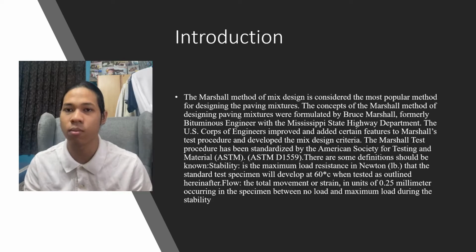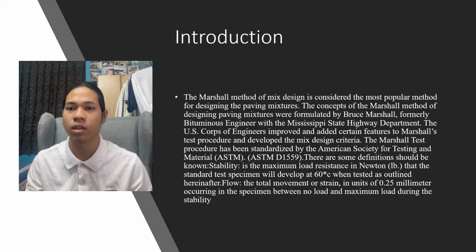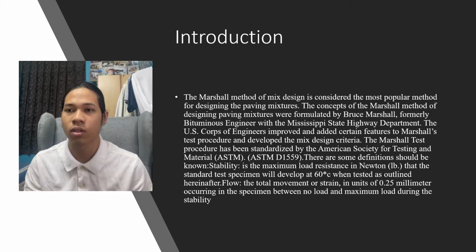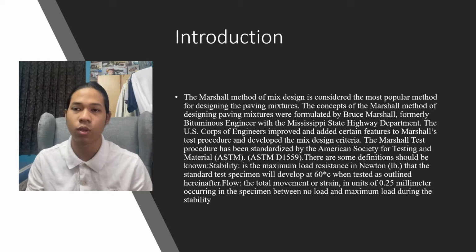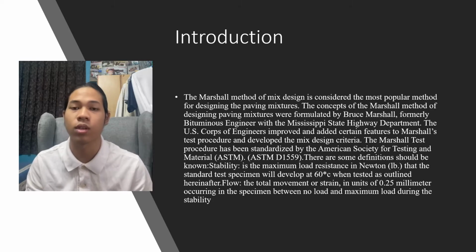Stability is the maximum load resistance in Newtons that the standard test specimen will develop at 60 degrees when tested as outlined hereinafter. Flow is the total movement or strain, in units of 0.25 mm, occurring in the specimen between no load and maximum load during the stability test.